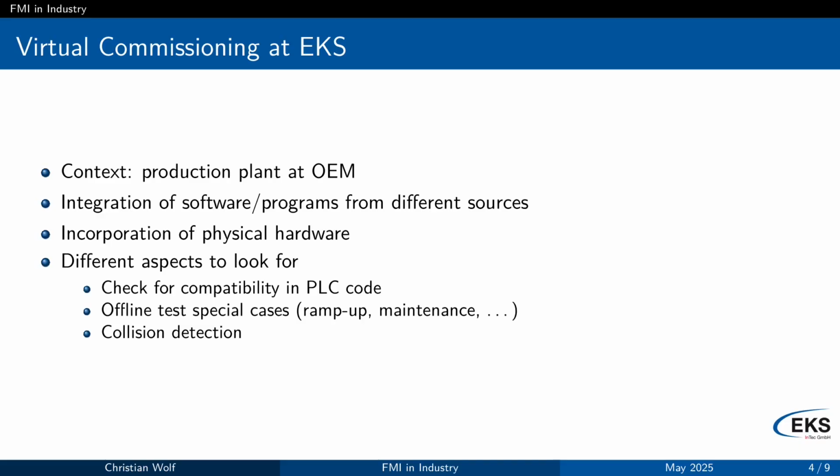Doesn't matter what it is, just a small thing that gets the system out of sync. Or someone opens a door, could also be the case. So the complete system gets out of sync, and ideally the robots would have a collision avoidance, there are so-called collision zones.